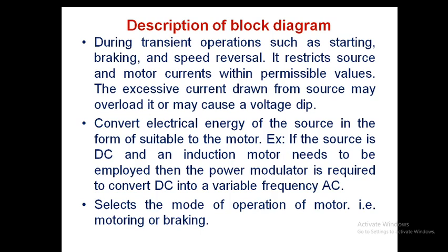Next one is it converts the electrical energy of the source into a form suitable for the motor. That's what I have told. If the source is DC and an induction motor needs to be employed, then the power modulator is required to convert DC into variable frequency AC.